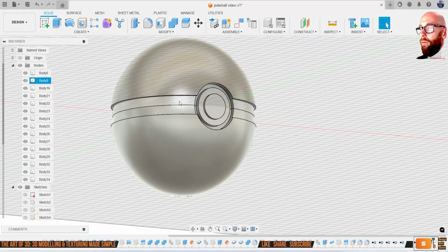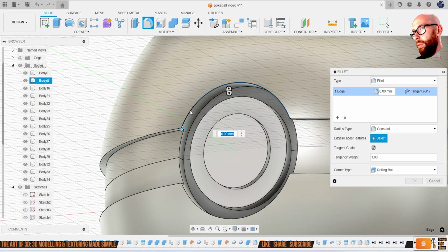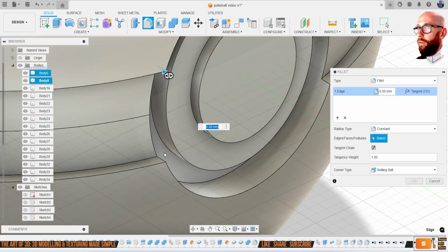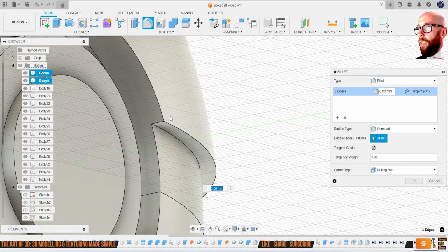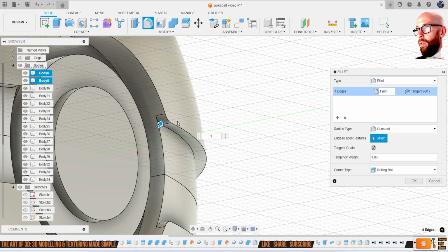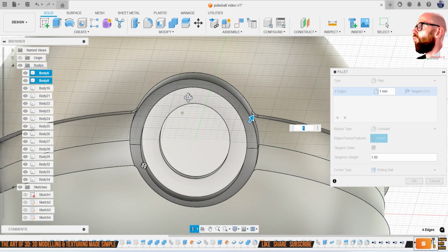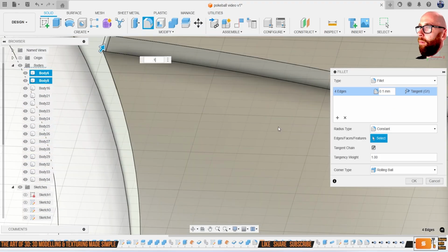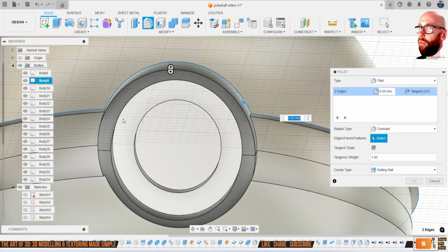Okay, let's fillet some edges. I'll do that one. Do a very small fillet on these first, because the modeling side is pretty much done. So then we'll jump over to Blender to have a go. Let's do our big one. Is that acceptable? I feel like it's just a bit sharp, doesn't it? Tell you what, let's try it without and see how it looks. 0.5.